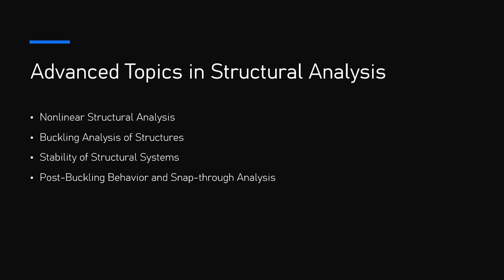3. Importance of post-buckling behavior. Post-buckling analysis is essential for safety-critical applications, such as in aerospace structures, bridges, and tall buildings, where the structure may experience significant loads after the initial buckling event. Designing structures to account for post-buckling behavior can improve their resilience and avoid catastrophic failure by ensuring that they can continue to carry loads beyond the point of initial instability.